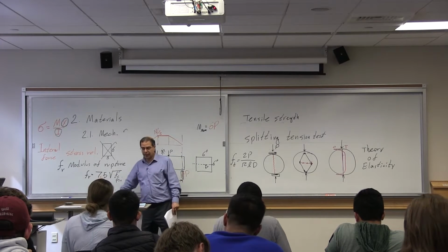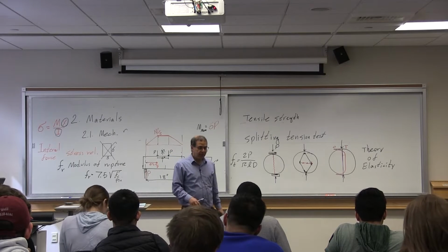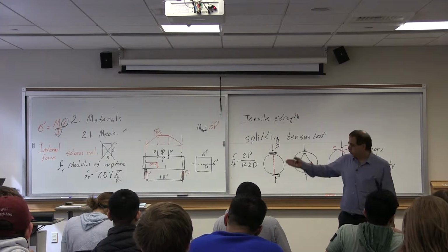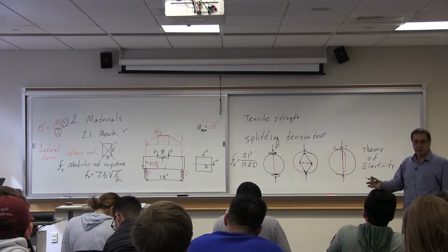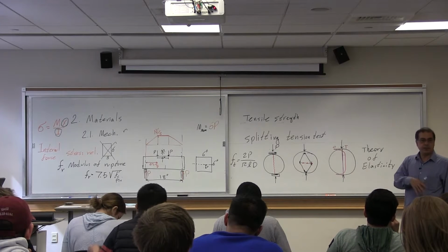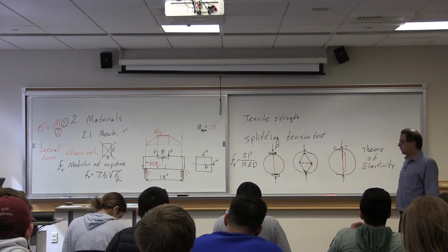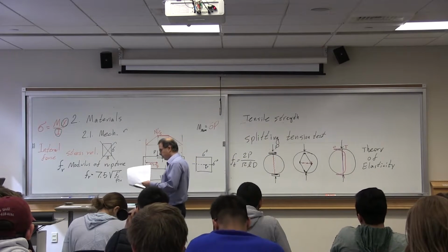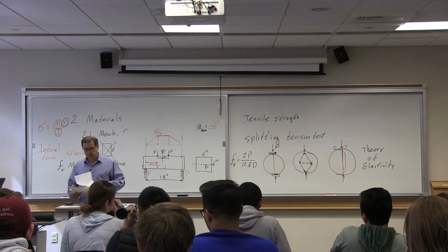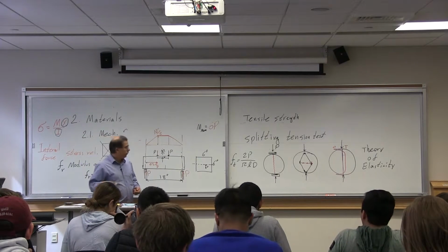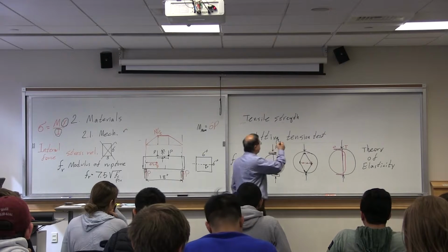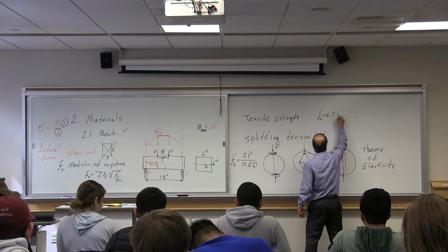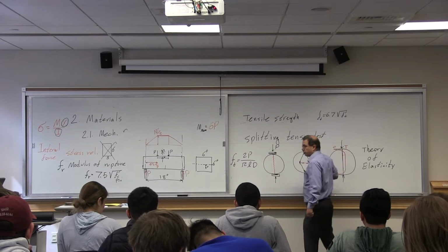This gives you a tensile strength approximately 10% of f prime c. Of course, you can do a more accurate calculation, just calculate it and see what you get. Sometimes a little bit less, sometimes a little bit more. So you can use this one to calculate the tensile strength. f of t is approximately 6.7 root of f prime c.